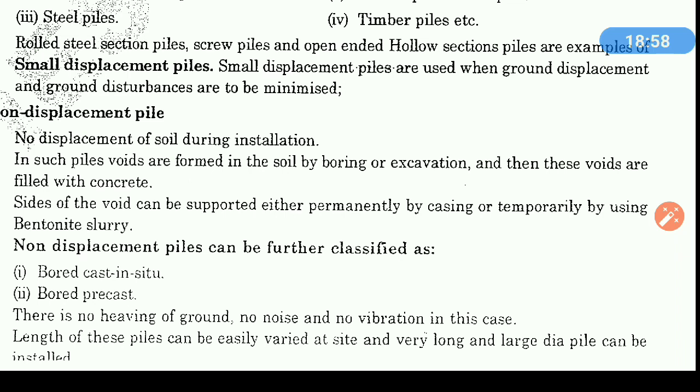The sides of the void can be supported either permanently or temporarily by casing or by using bentonite slurry. Bentonite is a type of clay which has quite high swelling and shrinkage properties.